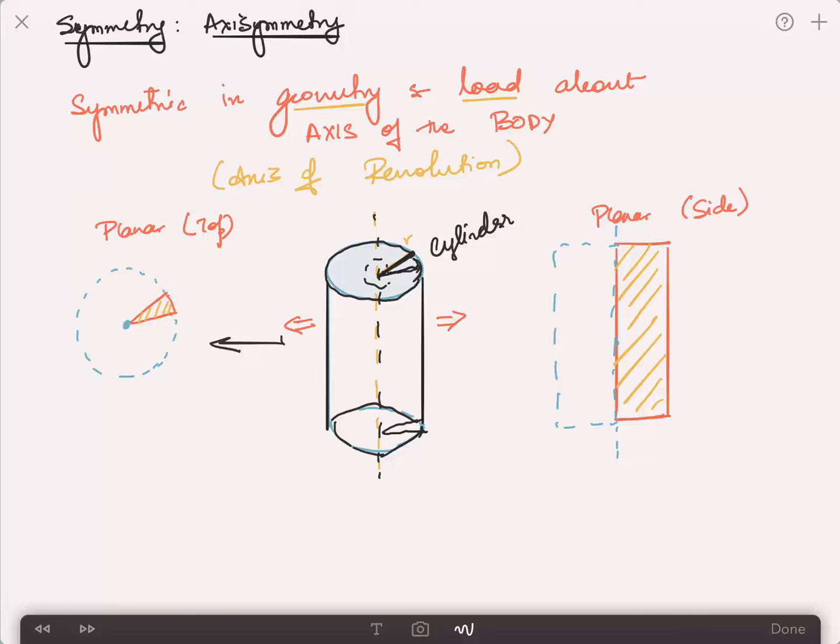And what you need to do therefore now is to also ensure that you have axisymmetric boundary conditions. What's good about Abaqus is that it automatically applies axisymmetry and symmetry as long as you provide the axis of symmetry. And then you don't need to think about it, but before going into the software, I want you to think about it and form some symmetry choices. Now before we go there, in the same way for this cylinder, I can find another sort of symmetry or axisymmetry which can be set up.